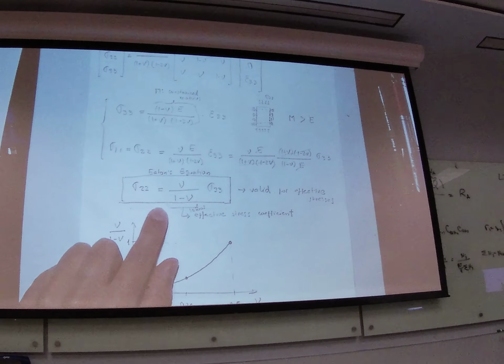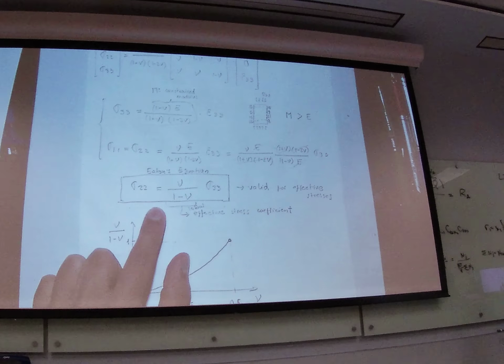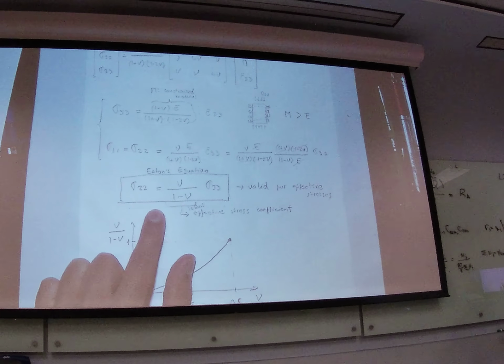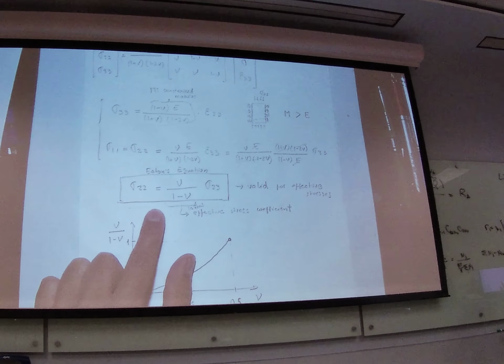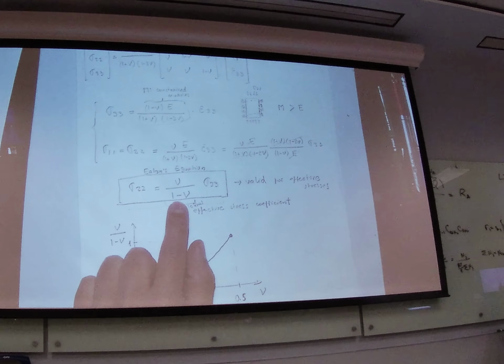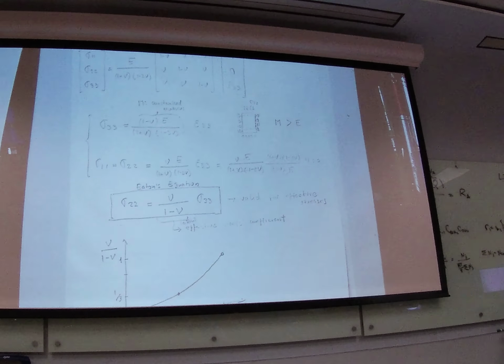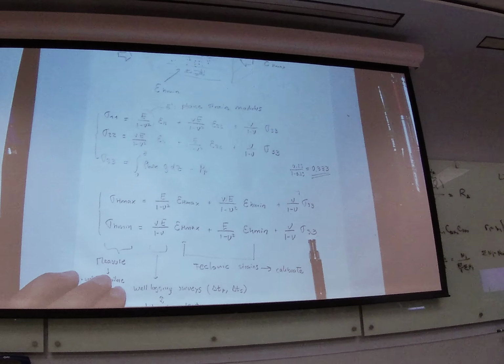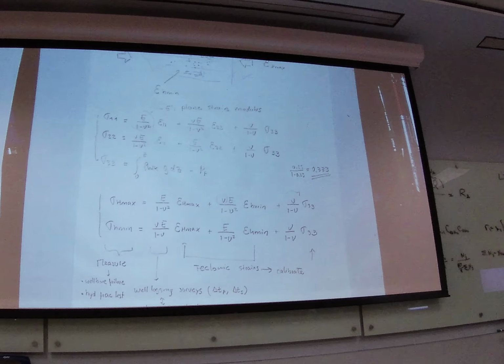Something alternative that we're going to use later on to estimate horizontal stress is another type of equation that was proposed by Zoback, but not based on elasticity, but based on failure. And we're going to see that that coefficient is similar, but also depends on the location, depends on the tectonic stress. So this 0.33 is just valid for conditions in which there is a normal faulting stress regime and there are no tectonic strains. If you don't have those, then you need to go through this larger development.